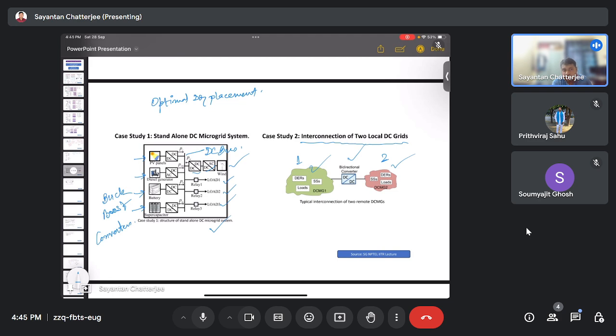If it is needed to share the load amongst these converters, then what we try to do is stage the load bus accordingly, and this we can also say is a networked microgrid. Okay, these two microgrids are networked with each other. The advantage that it provides is that the system becomes cost effective. The system also becomes reliable.